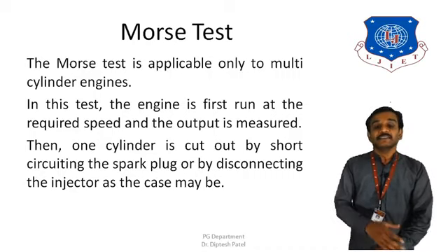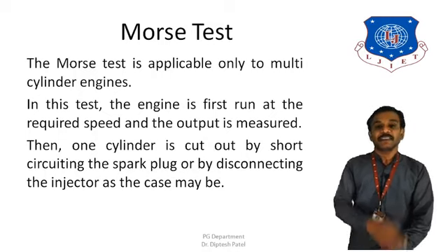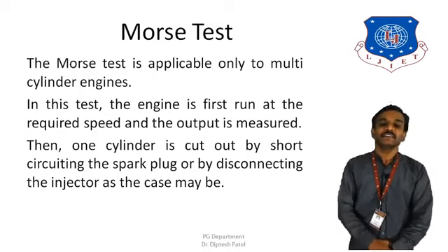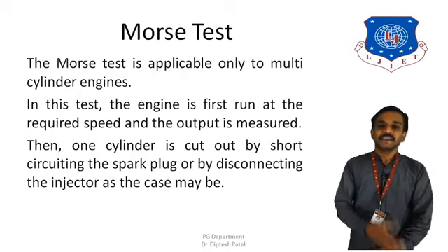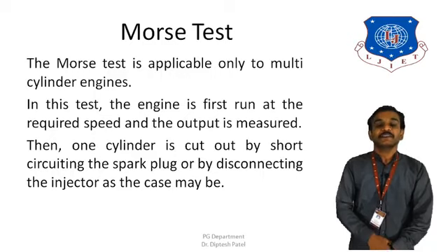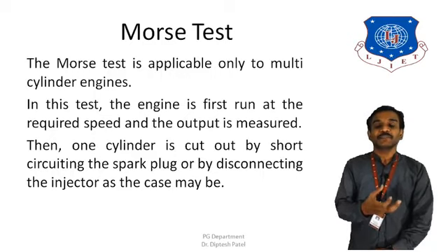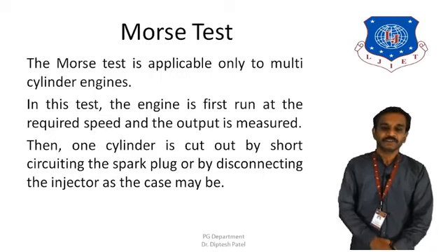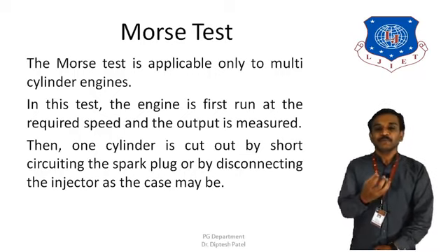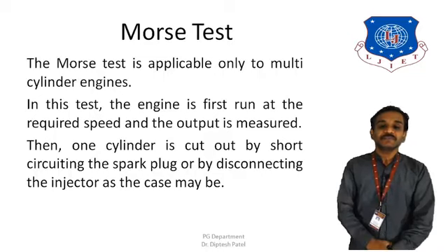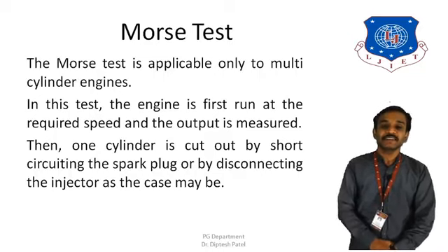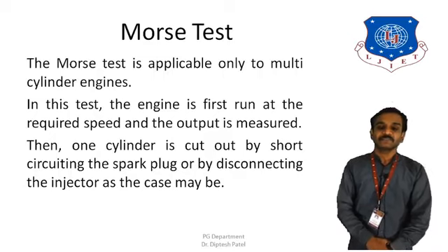And the friction power would be the same, because all of the 4 cylinders are still moving up and down in the cylinder, so the friction would be the same as it was in the first test, but the power of the one cylinder would be reduced. So both speed and power will reduce, while the speed is adjusted and mostly kept the same as the previous test by adjusting the throttle.